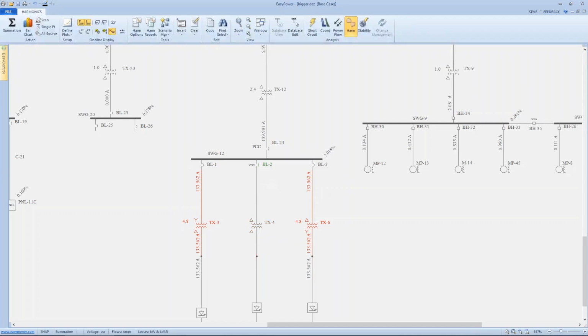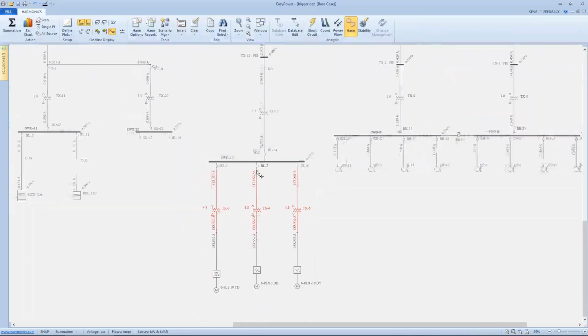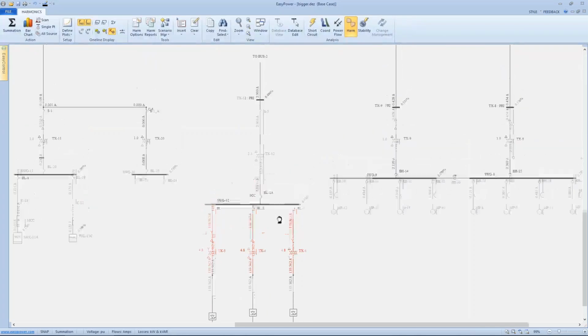You can see the difference it makes when I take out one of these legs. If I reduce that leg that was at 0 phase, you can see it actually doubles my harmonic content as a result. So this is a method of phase shifting the pulses and canceling the harmonics that are a result of it. That's one mitigation technique that we can simulate, and that saves us because it can be done as part of the drive system in the VFDs.